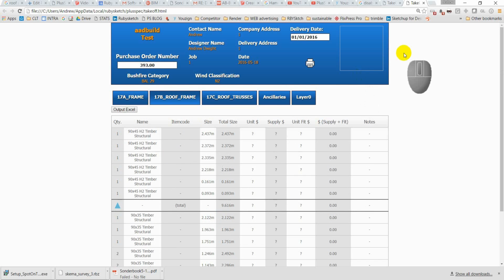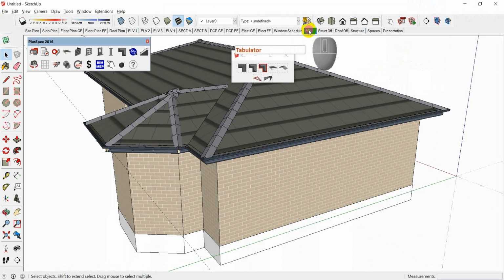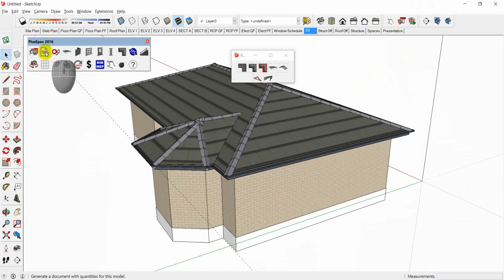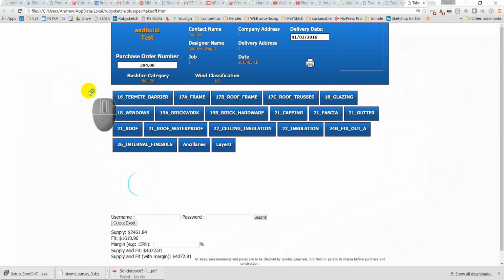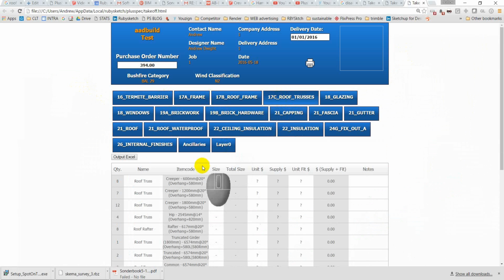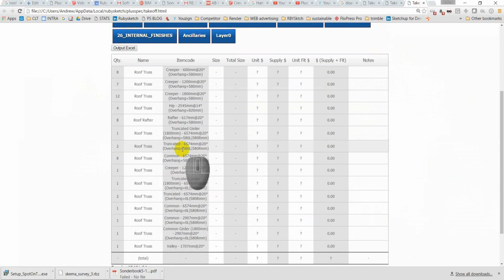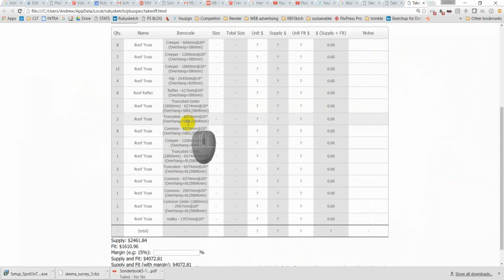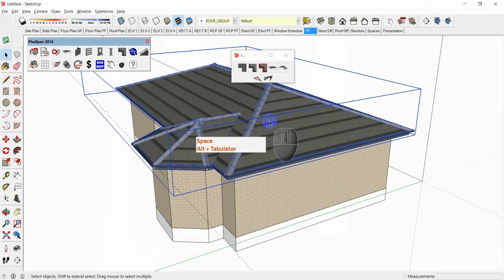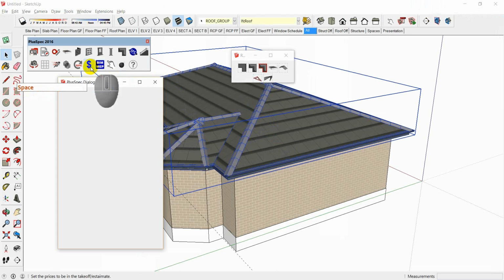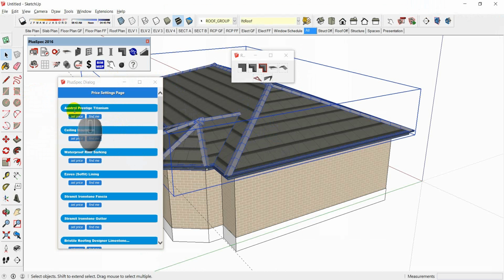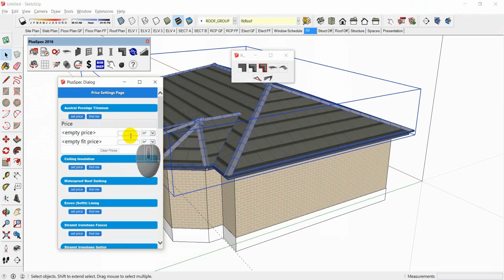Okay, if I go back to all here and I did a takeoff, you'll notice that I'll have windows and everything, roof trusses, the width of the roof trusses span from the creepers. Right, the pitch, you can go and associate price. So inside of here, if I click on this and I go to this dollar symbol here, I can go and put in prices. So here's my roof tile. I can set my price, how much I pay for it. I don't know, it might be $20 a square metre, and I might pay the roof tile as $20 a square metre.